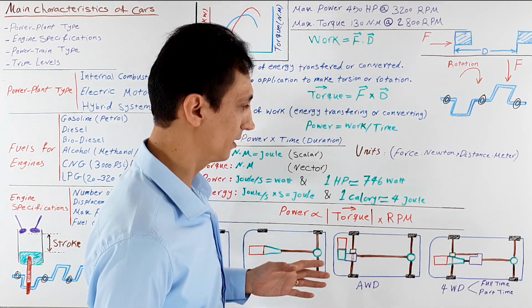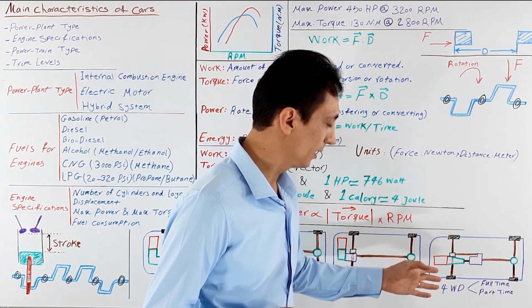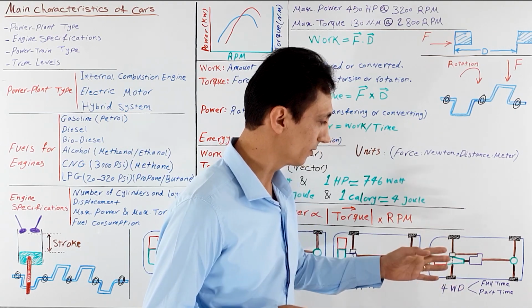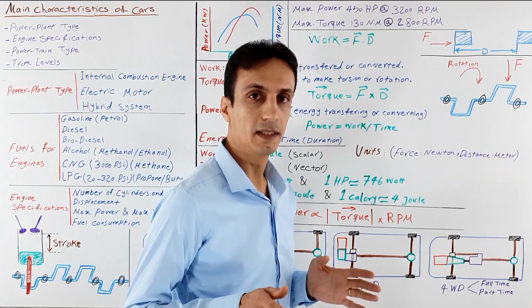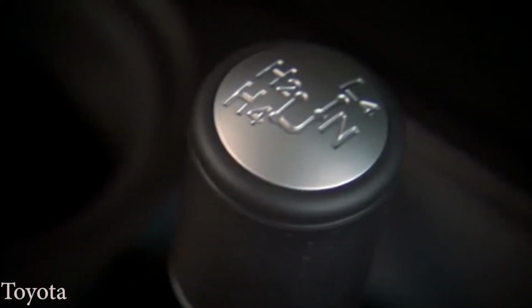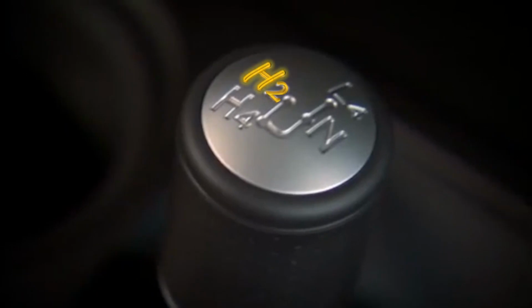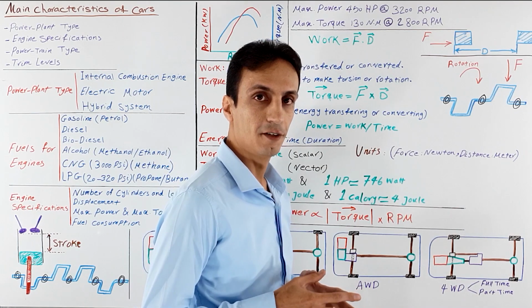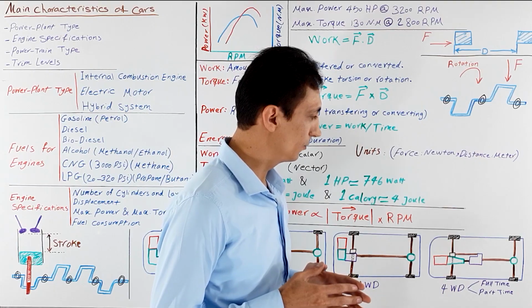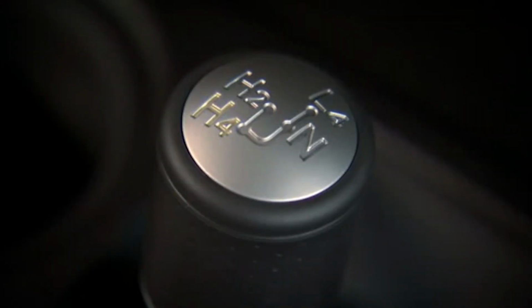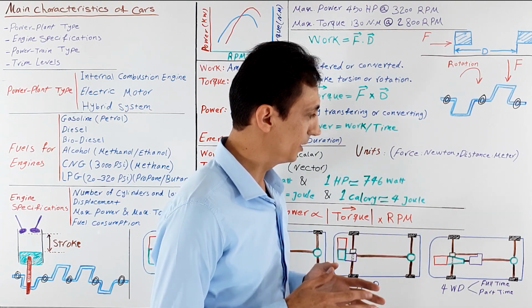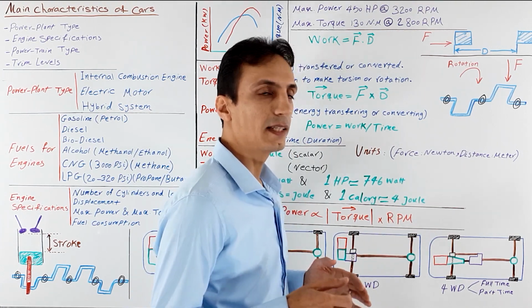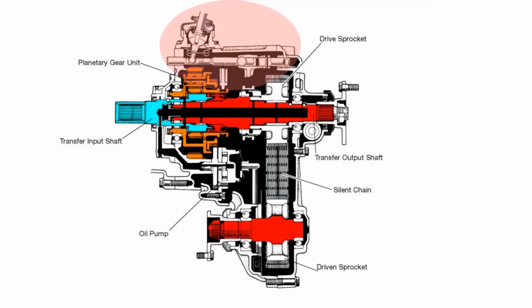Also in the market there is another design for four-wheel driving that is part-time four-wheel drive system, and this system is a little more complicated in the way that engagement works in transfer case, and we usually drive this system in two-wheel drive mode, but there is a button or shift stick for the driver to go into four-wheel drive in high speed or low speed mode. Traditional part-time four-wheel drive systems were using mechanical means and gears and chains to select modes and speeds.